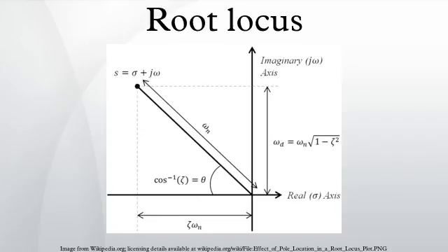Example: suppose there is a feedback system whose input is the signal X(s), and output is Y(s). The feedback system forward path gain is G(s). The feedback path gain is H(s). For this system, the overall transfer function is given by. Thus the closed-loop poles of the transfer function are the solutions to the equation 1 + G(s)H(s) = 0. The principal feature of this equation is that roots may be found wherever G(s)H(s) = -1.